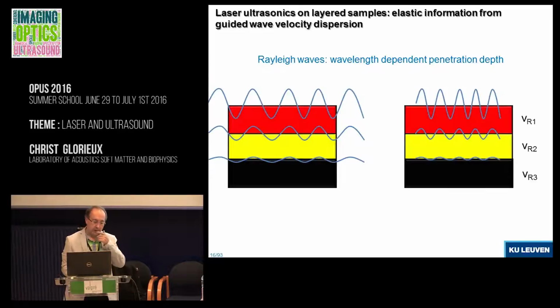As I said before, the interesting thing about these surface waves is that they have a penetration depth similar to their wavelength. This is not really a correct drawing, but I try to show that the penetration depth at the long wavelength is deeper than the penetration depth at the short wavelength. The amplitude actually doesn't matter; it shows that the amplitude is going down with depth.